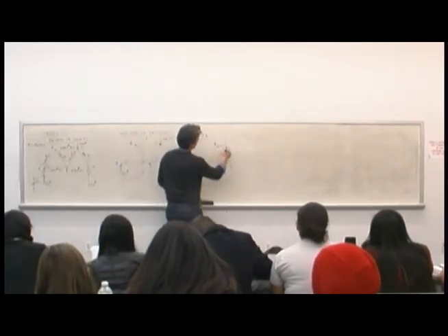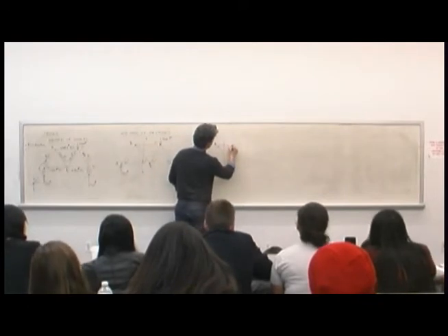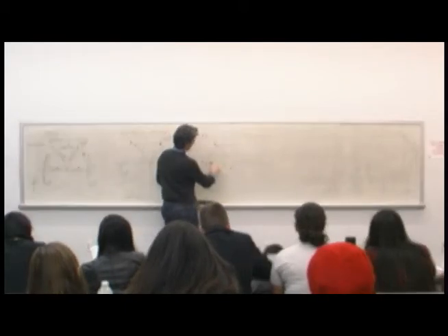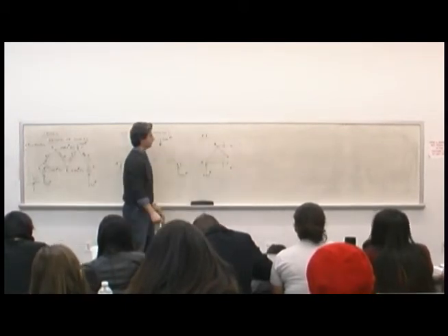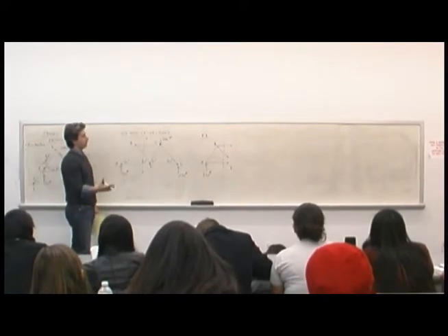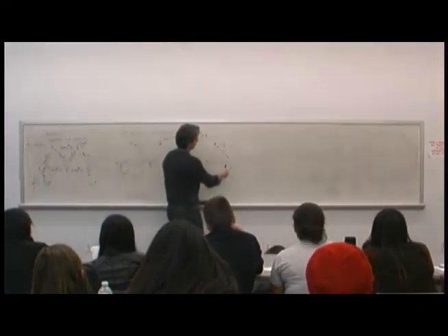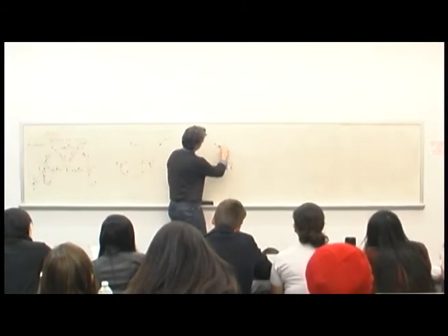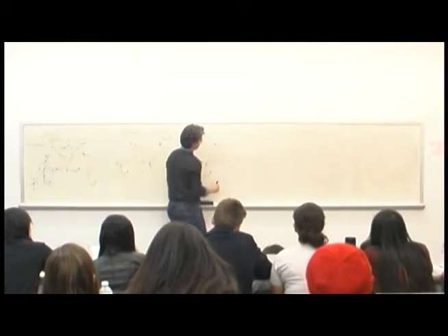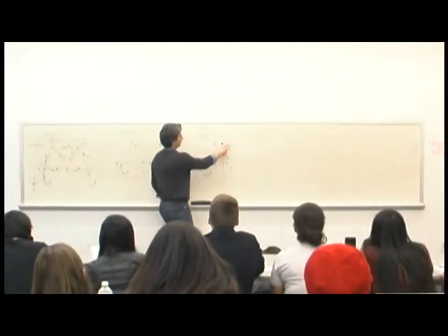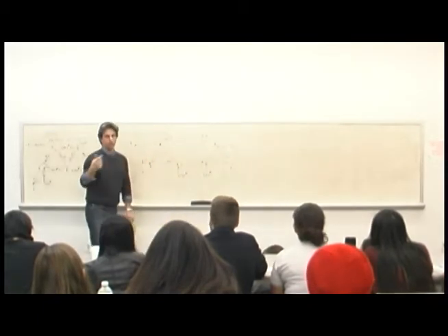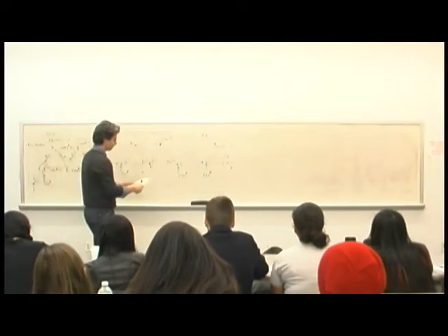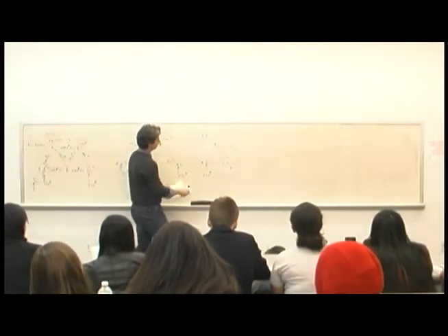So I want to cut through BC and show a force. Cut through BE, show a force. Cut through AE and show the internal force. I don't know what those forces are at this point, but I know that these two members connect to point E, over here. This member is connected to point C over there. But I can now isolate particular forces, and using equations of statics, I can solve for the particular unknown that I'm looking for.